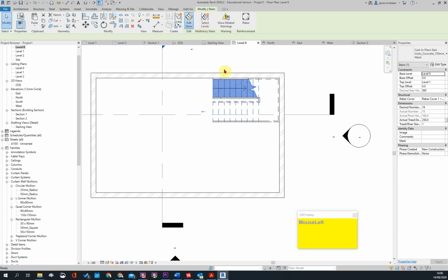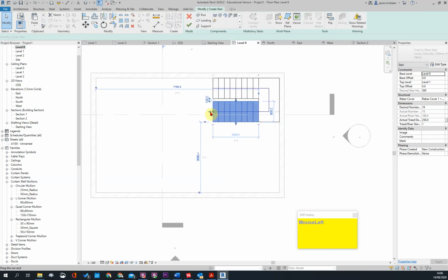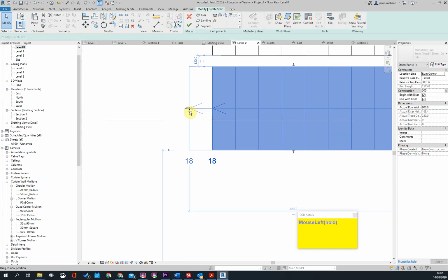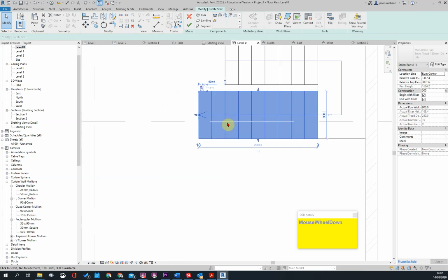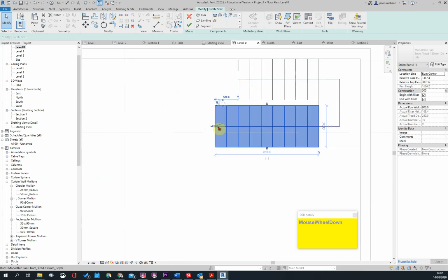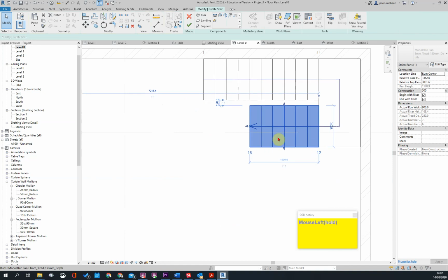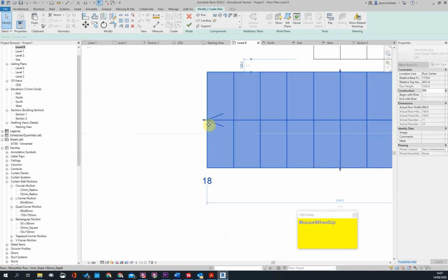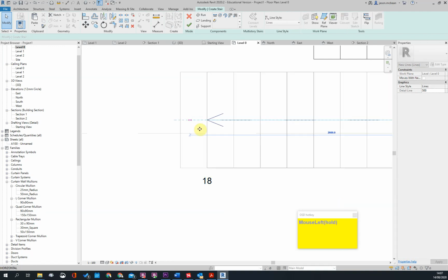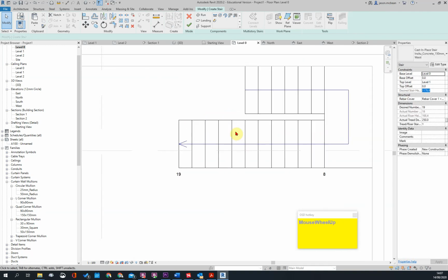So here I'm going to go and say edit staircase. So here, if you grab this point, it'll add one more riser. Oh no, sorry. So the arrow will take from the bottom. So this is how you readjust the pattern. Okay, so here I want these to match. And you grab the dot and it'll add one more riser. So it's one more riser.